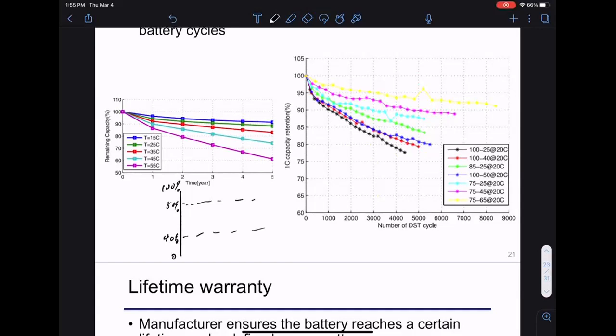So what's mostly preventing batteries from making money nowadays? There's a lot of operational consideration. Basically, what the battery wants to do is sit at 50% charge all the time. It doesn't want to be charged or discharged, it doesn't like to be very full or very empty, so it likes to sit at 50% and not do anything. That's best for battery capacity. But obviously that's not a very useful battery.